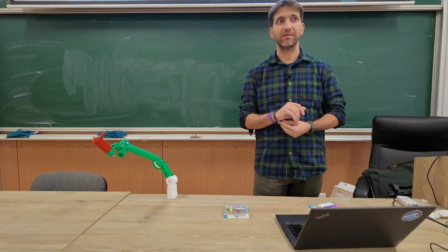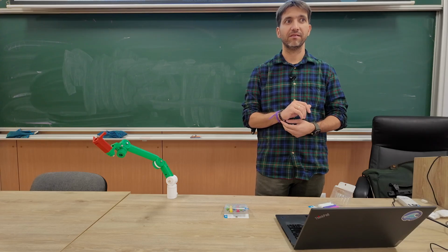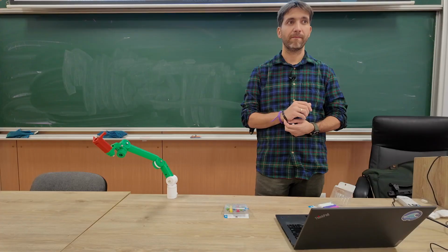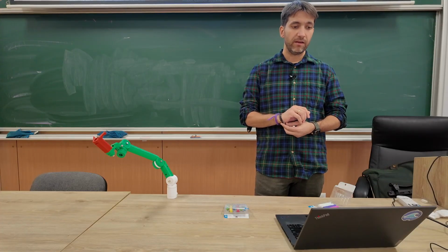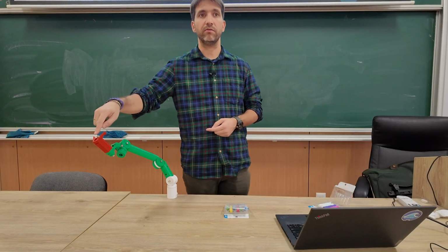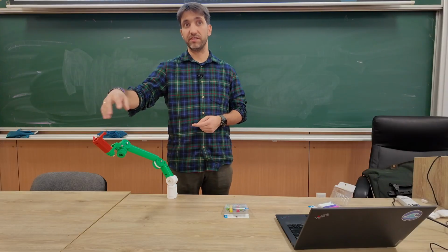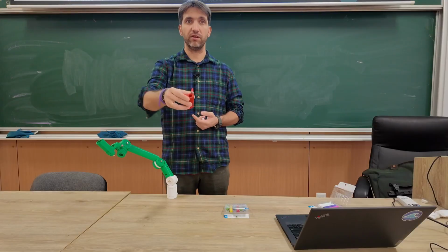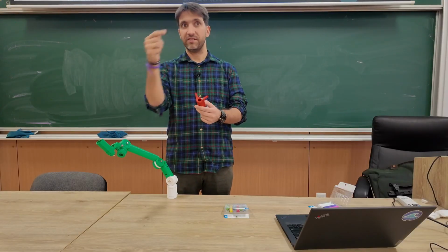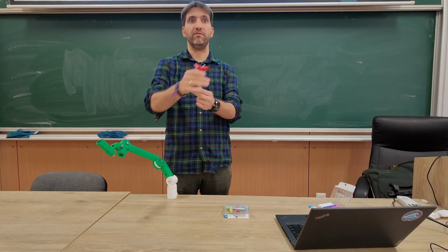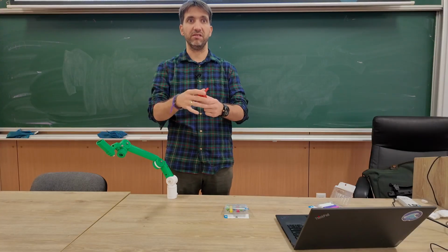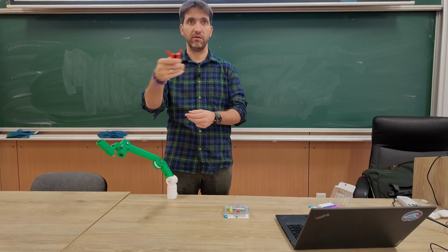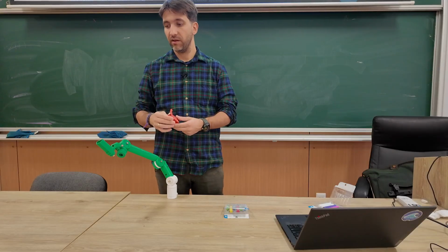I was thinking to apply a PID for the end effector and then find the joint coordinates using inverse kinematics. Yes, but we said that the end effector itself is not single input, single output, because if I want to control the trajectory, it's not just one set point I have. I have the 3 coordinates, the 3 rotations, so I basically have 6 set points, 6 references.